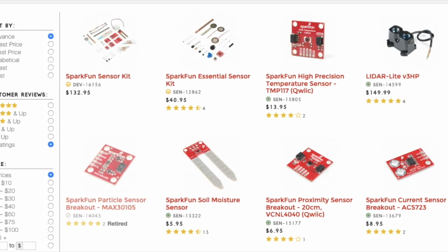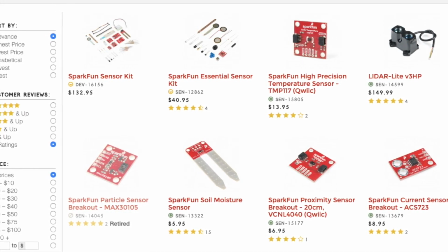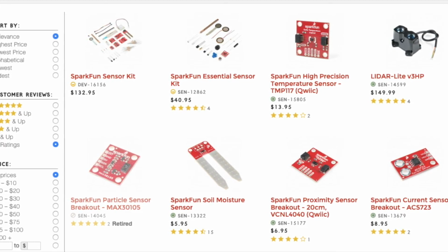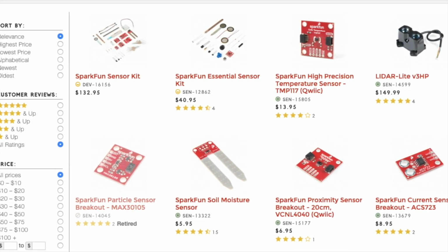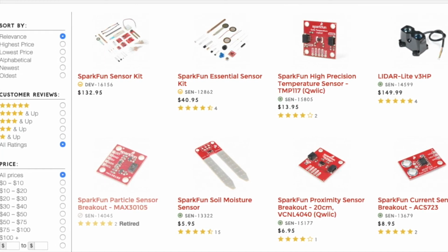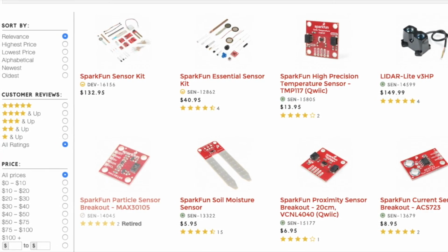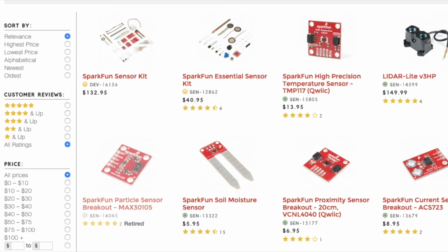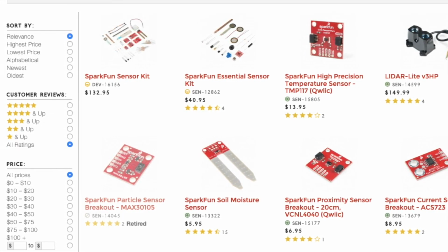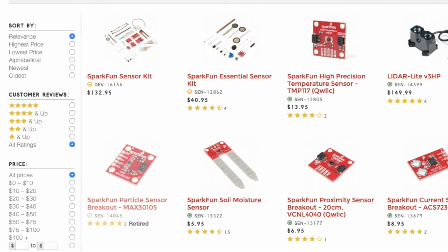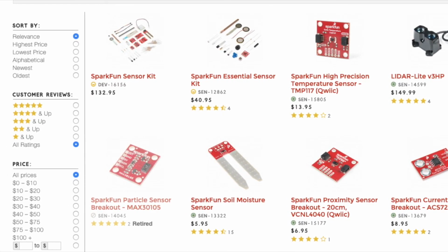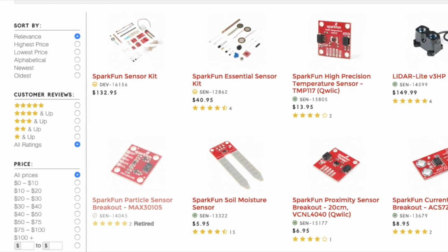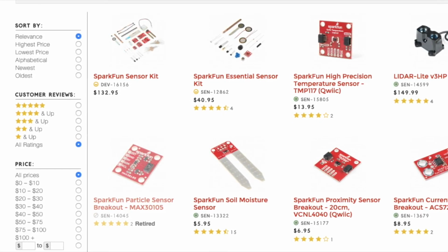The GPIO pins on the Circuit Playground Express run on 3.3 volts, like most Teensies, while the GPIO pins on an Arduino Uno or a Mega run on 5 volts. While most output devices built for 5 volts will work okay at a 3.3 volt logic level, like our NeoPixels, some input sensors are built for a 5 volt logic level and won't work at 3.3 volts.